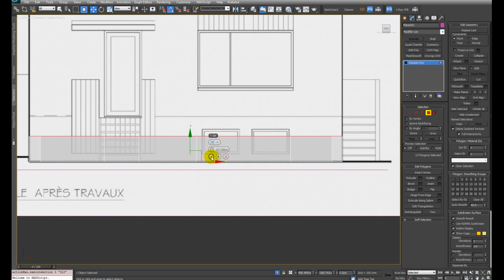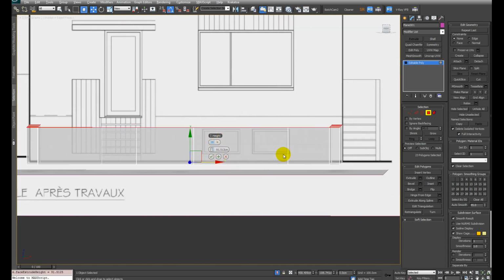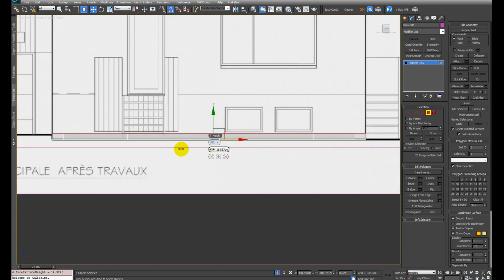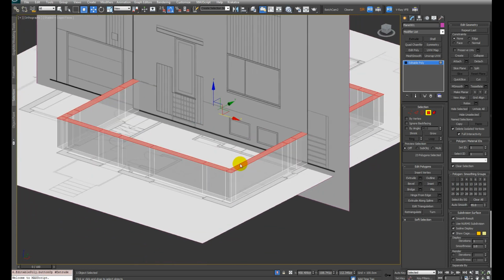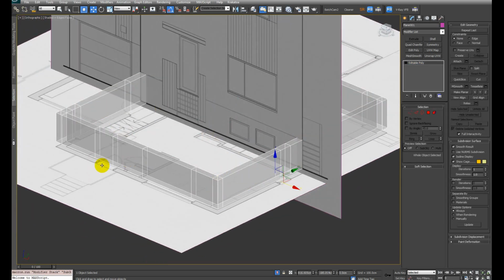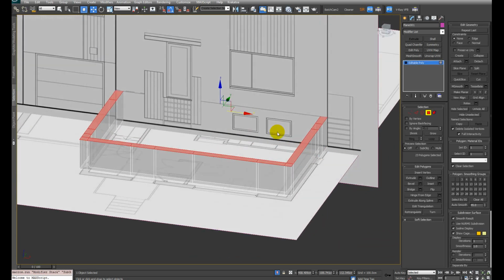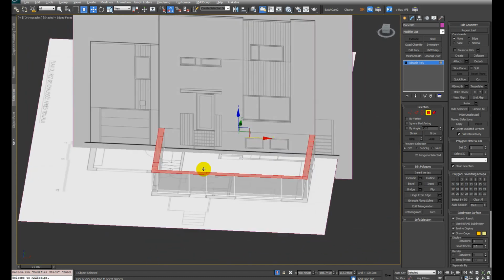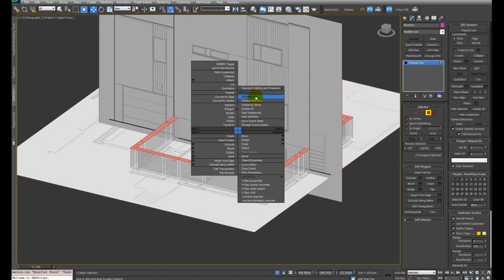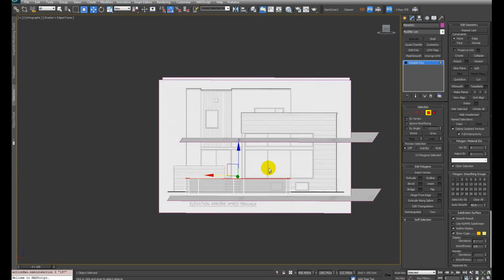And if I go into the front view, let me see, I want to extrude to this height first. No, actually let's extrude until the door height, to this height. Alright, click OK. You can see that right now I can see through my object, and the shortcut to enable see-through is Alt-X, so that's useful sometimes. Alright, go back into the polygon mode, and now let's bring back all the other planes so I can see better what's happening here.